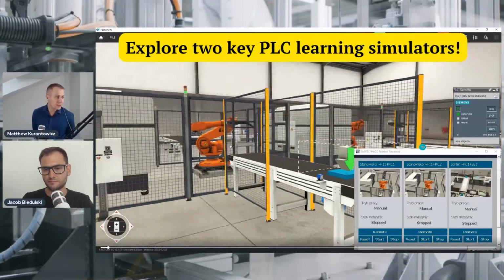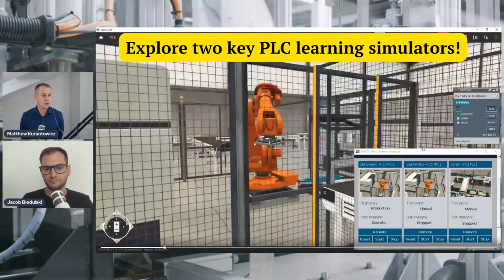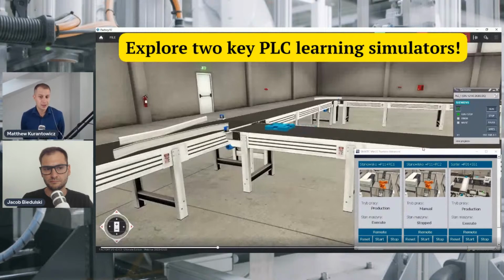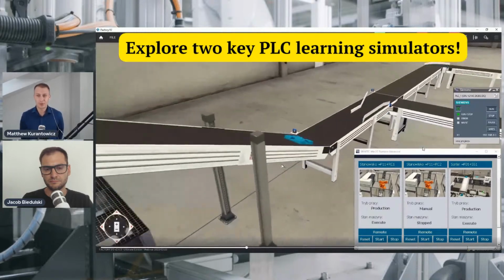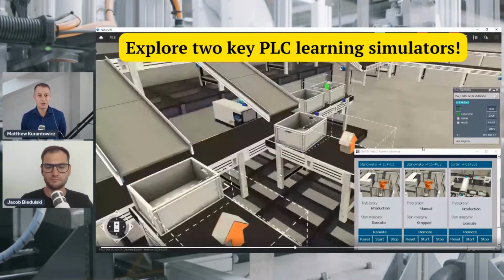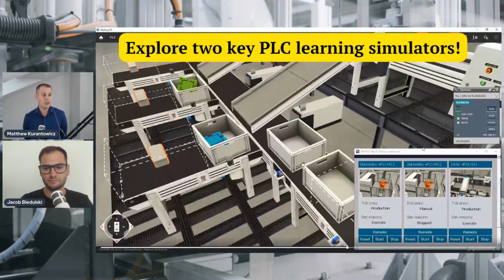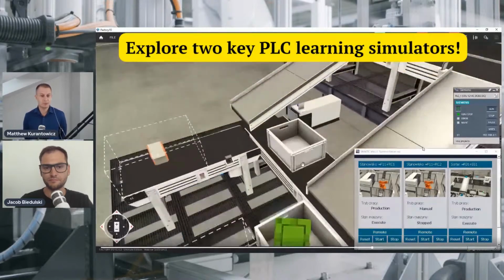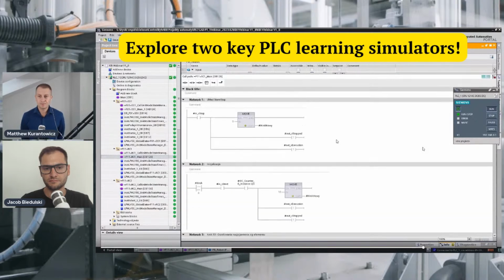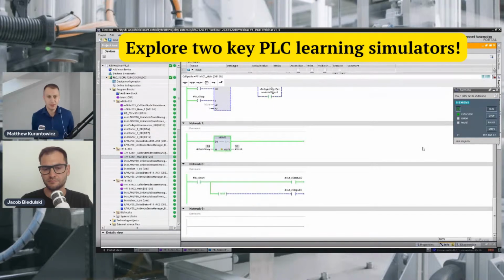Okay, so let's go back to our topic. Firstly, we would like to show you your learning path. The best way is to install free software, which is TIA Portal from Siemens. You have PLCSIM, and you can connect that with the virtual Factory IO system. This is a 3D simulator. You can simulate conveyors, robots, and many more. You can connect that with PLCSIM, and that's all.